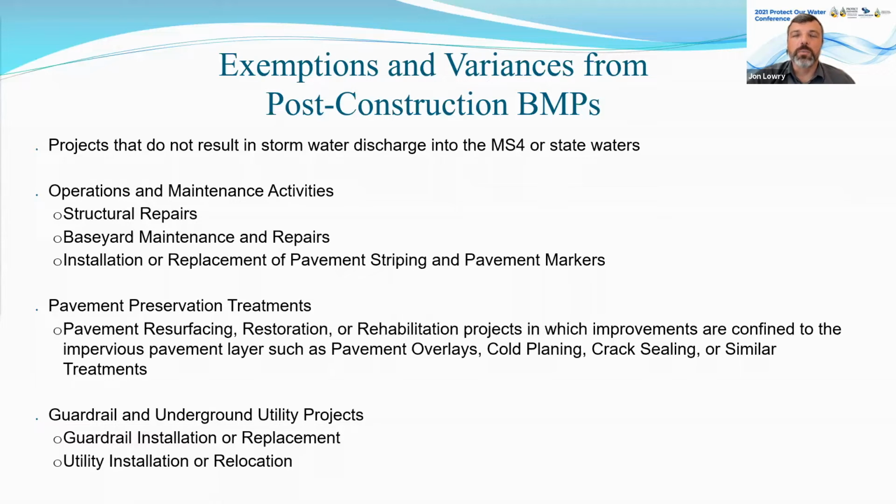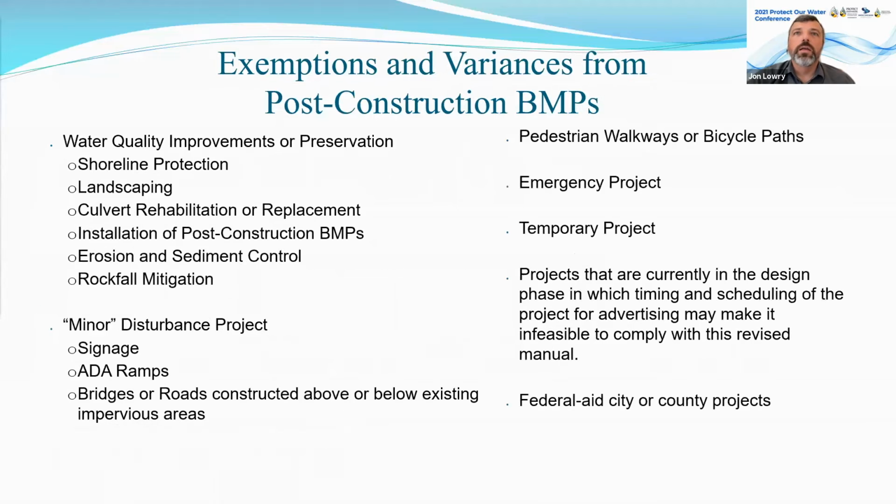Those projects that are usually just a linear trench down the center of the roadway, those are usually exempt. Next slide. And then a couple more: water quality improvement or preservation projects, like shoreline protection, landscaping, projects that are meant to improve the environment or preserve or reduce erosion, typically exempted. Minor disturbance projects, like if you're just putting in signage or ADA ramps, bridge or road constructed above an existing impervious area, like some of the viaducts, pedestrian walkways, emergency projects, temporary projects.